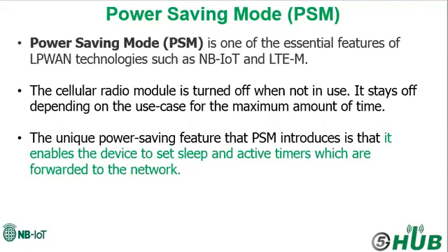The unique power saving feature that PSM introduced is that it enables the device to set sleep and active timers, which are forwarded to the network. The network keeps the device registered in the system for the set time, and if the device wakes up within that period, no reattach procedure is needed. The maximum sleep time is about 413 days, and the maximum active timer is about 186 minutes.